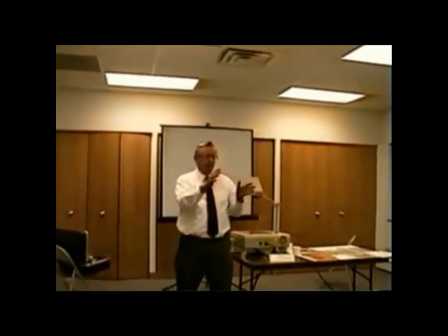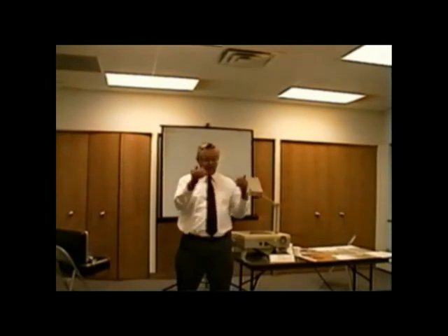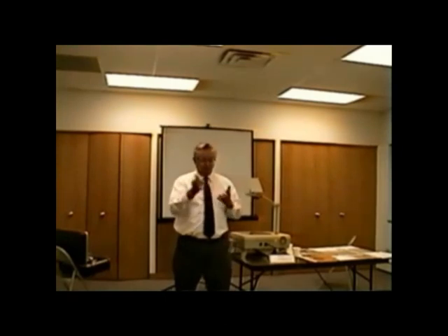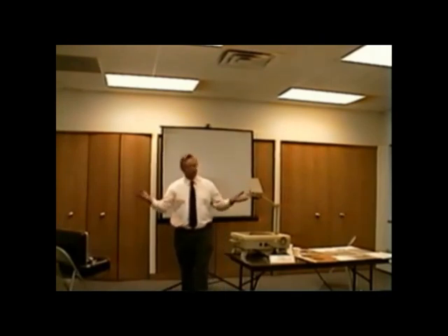Now, again, different opinions of different classes. We're saying that the maximum is 250 according to the book. We're saying to you that if you measured 175, is that okay to leave in? Yes. Now let's say you measured it, and we know maximum is 250, and you measured 210. Is that okay to leave in? Yes, according to what we know, right? But now let's say you had 241 ohms. Man, that's getting right up there, isn't it? Now the point is, ladies and gentlemen, this is where the technician's personality comes in.